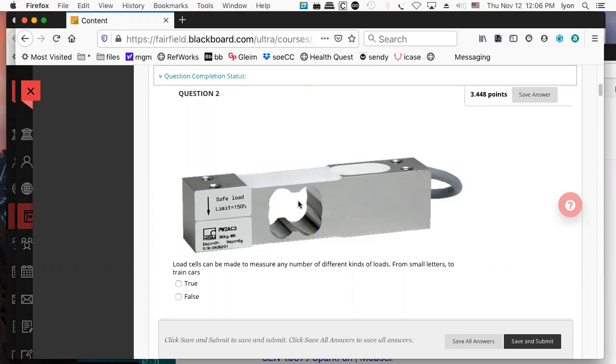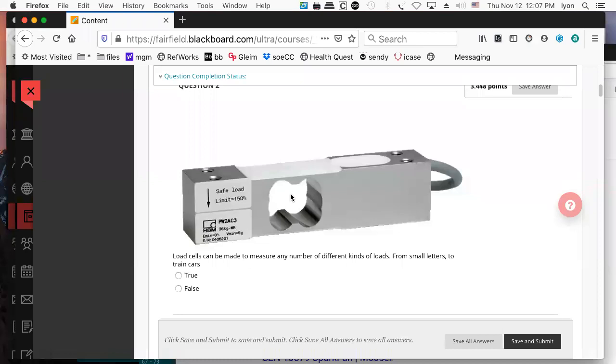Yield strength is the point at which the material ceases to do elastic deformation and then proceeds to do what they call plastic deformation. That means it doesn't return to its original shape. In other words, you're deforming it in such a way that it looks really bent. You don't want to do that with materials like the ones you're using to fly around in your helicopter. There's going to be a lot of vibration, but you don't want those things to deform permanently. So you want to be able to take the vibration.